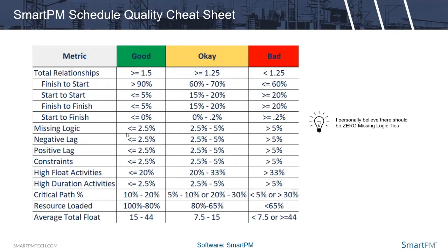The more activities that have a predecessor and a successor, the more logically driven a schedule, the more useful this tool can be for managing the work, because one of the other important things that happen through the updating process is that things do happen, other things don't. Things take longer, other things don't. And when you update your schedule at a given point in time, it actually tells you the plan going forward, which could shift the critical path. But missing logic makes it difficult. Missing logic makes it so your schedule's not as reactive. Like one activity, if it doesn't have a successor leading to another activity that's important, well, if that activity is delayed, the successor activity is going to, according to the schedule, think it's on time, and all of a sudden you've got a problem that you don't even know about.